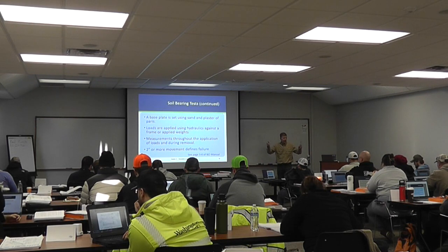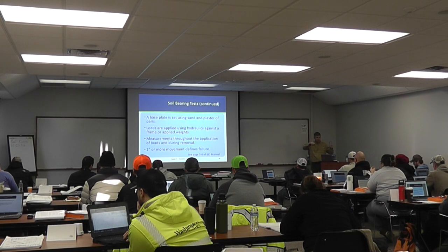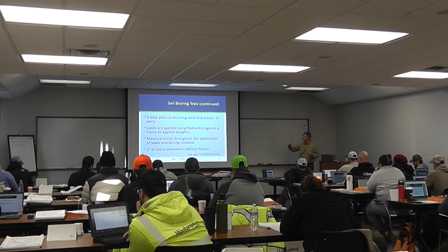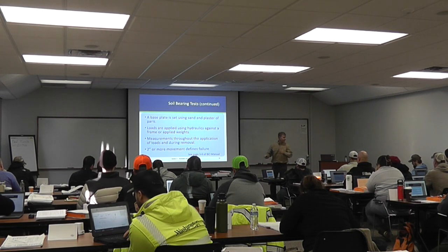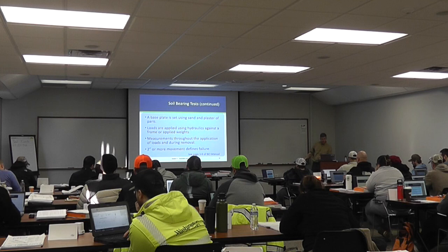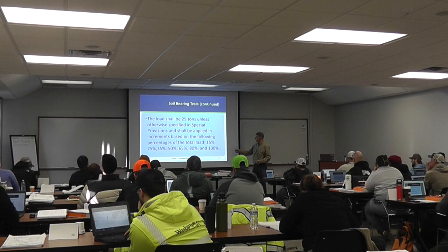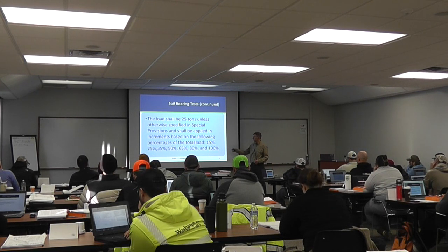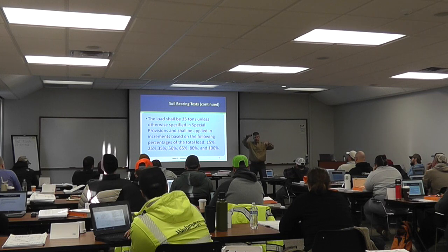Essentially, it's a base plate that is set. You apply loads, you hold the loads for certain durations, and then you measure your settlement. You actually go down in a series of slides. So each load is 25 tons, and then we would hold that 25 tons at 15%, then 25 and so forth, all the way to 100. And you hold them until your settlement has stopped. If you push that load on there and it just keeps on settling, it's not a good sign.